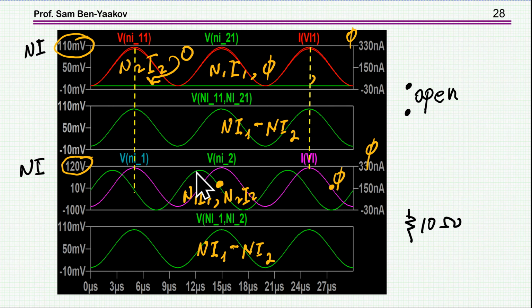So the main MMF is related to the input current, while the reactive power is related to the difference in the MMF, which is very small. And this is what we have seen before. So this is the driving force for the flux, in fact, while these two MMFs of the input and output are equal and of course oppose each other, except that there is a small difference, which is this one, which we don't see because it is small as compared to the MMF itself.